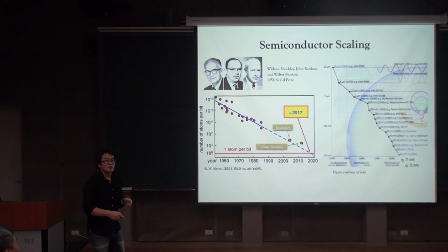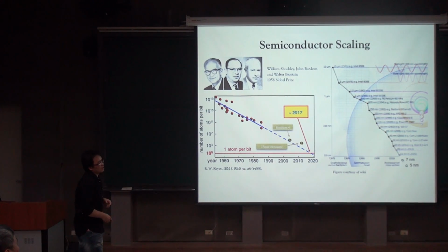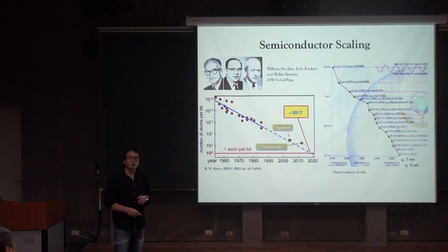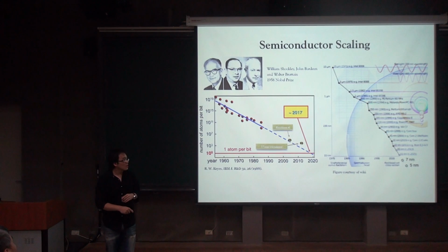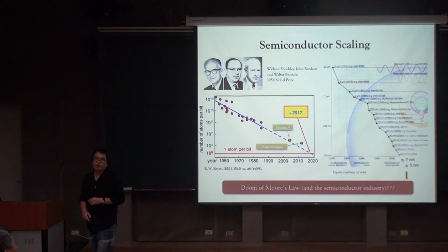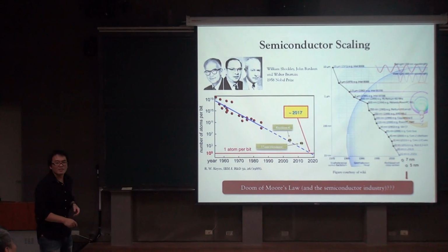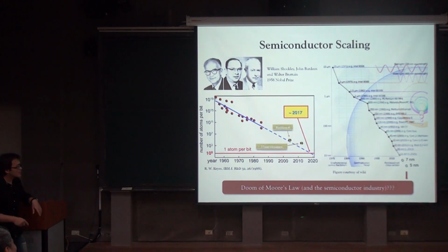Most theorists predict that the end of the transistor is probably 5 nanometers. If the gate is smaller than 5 nanometers, there is no way to turn off the transistor, and you cannot control the 0 and 1, the digital on and off. So I always say, when I'm giving a talk, I use this as probably the theme of Moore's law, and possibly the semiconductor industry.